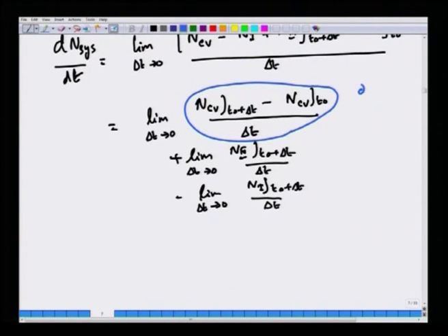This is nothing but the normal partial derivative of the integral of n, Cv, eta rho dV. We could also just keep it like this. This is the usual partial derivative of n Cv dV, the rate of change with respect to time of the amount that is present in the Cv of the quantity n, which could be mass, momentum or energy.